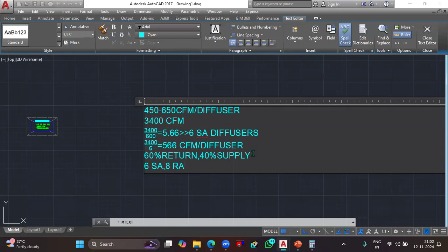Once you got this value, now let's discuss the inner neck data and outer neck sizes. I told you guys, generally the outer neck size that we can take has to be 2 cross 2, which is 24 cross 24. It simply means 24 inches by 24 inches. It is the grid ceiling, I told you that day itself. So this value is very viable and directly taken from the existing conditions. But what about the inner neck sizes?